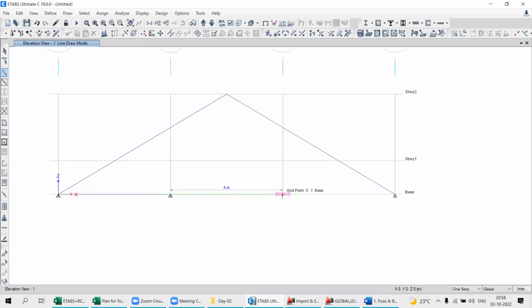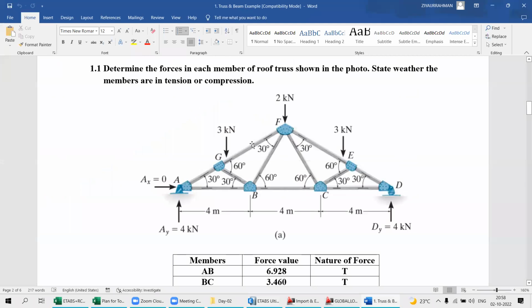Okay. If you have any confusion and doubt, you can see your drawing. Each individual element, each element is individual. All the elements are connected at the particular point. If you say that I take a continuous line from A to F, that will be wrong. At every joint your truss element breaks. That is the assumption. Okay. All the elements are connected at their ends.